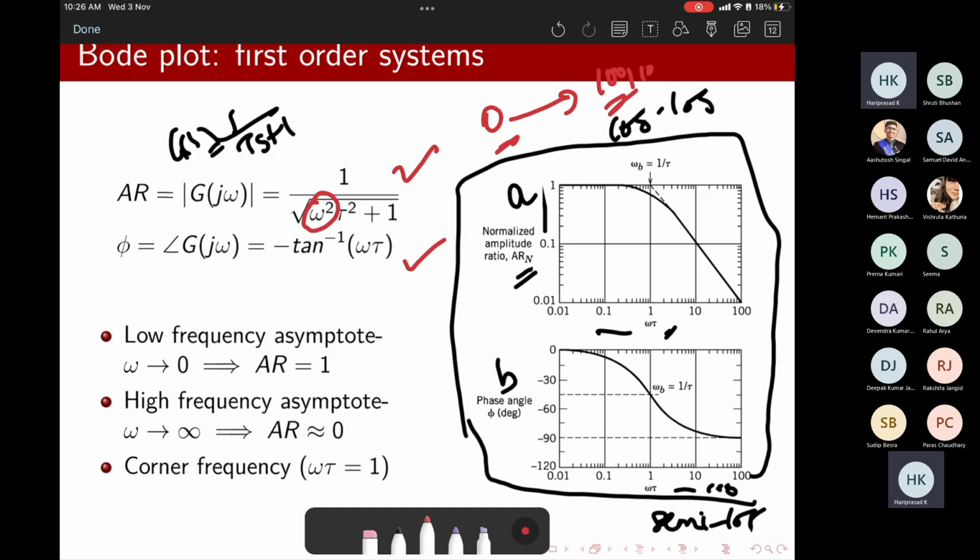Okay, so if you start putting it in the normal graph, you will not be able to do it because your scales are limited. So a log plot in that case is an easy solution. Okay, so whatever you see over here, the solid line, is something known as the exact Bode plot. So exact Bode plot essentially means that you are computing every point and plotting it.